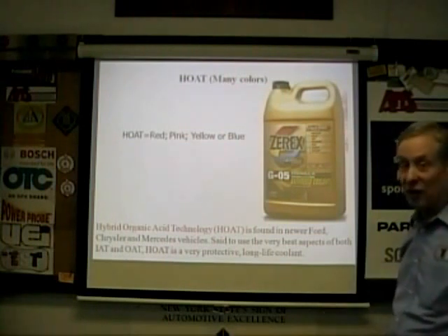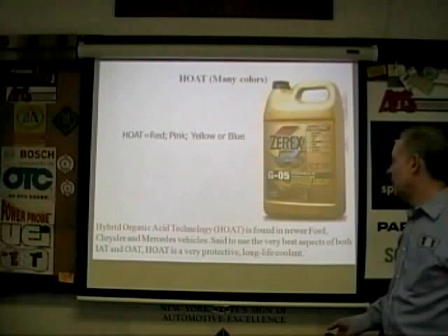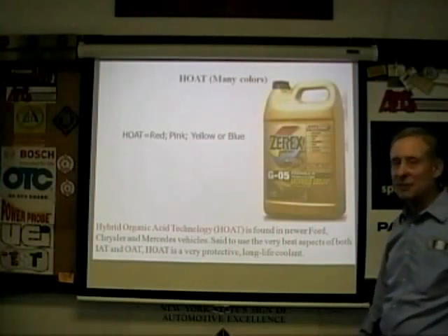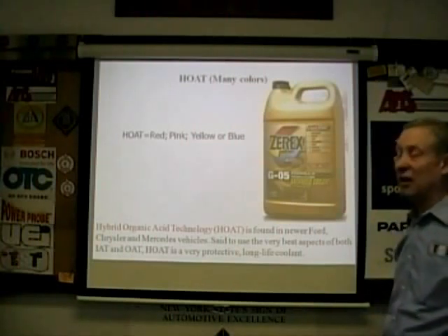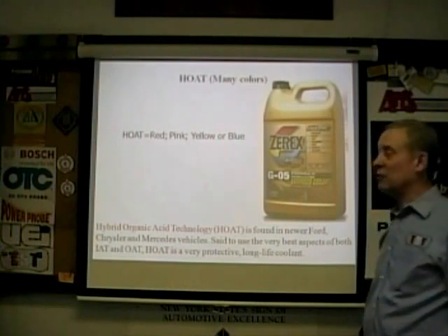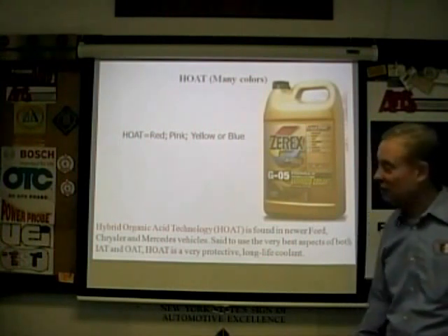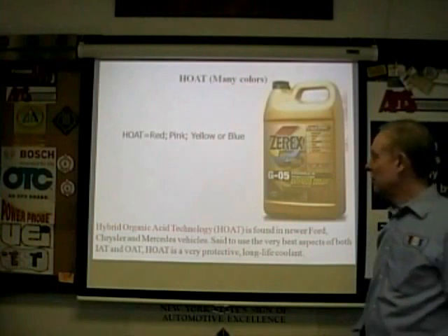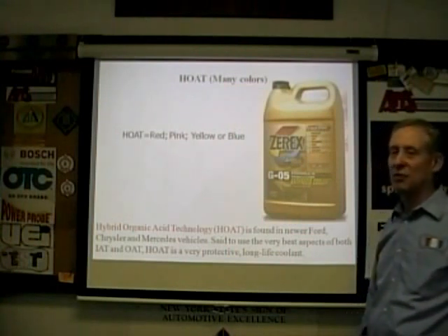You see here, Ford, Chrysler, Mercedes. It's supposed to combine the best aspects of IAT and OAT, and I'm sure it does. They want to give you this lifetime don't ever change it thing. Again, I disagree with that. Change the coolant. Put the customer on a schedule.